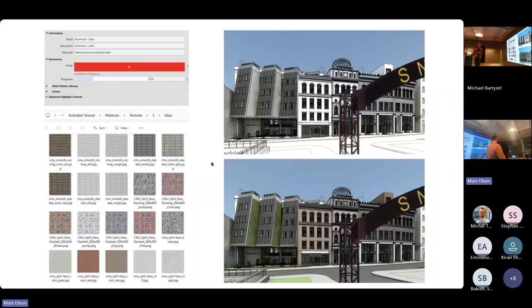Image maps are linked to the Revit model that they're used in. So this is our first pain point, really, that they don't travel with the model that they're linked into. And this is a common pain point where you'll download a texture file from an online source, have it in your downloads folder, link it to a material, and then it can't be accessed by others.